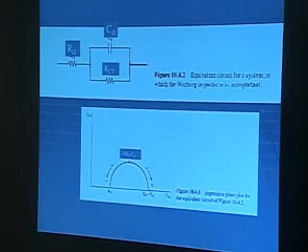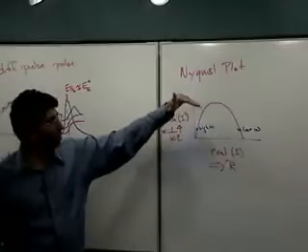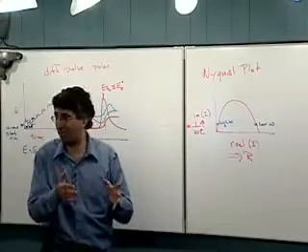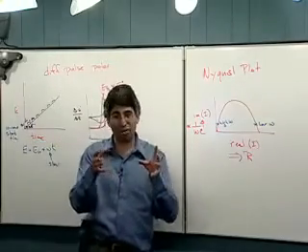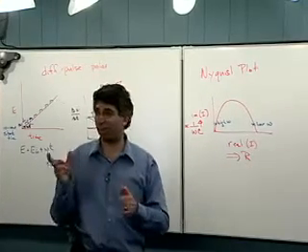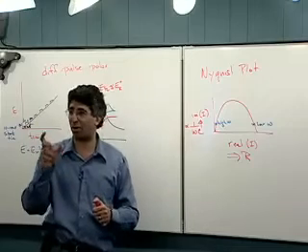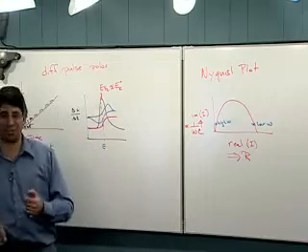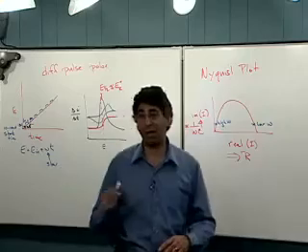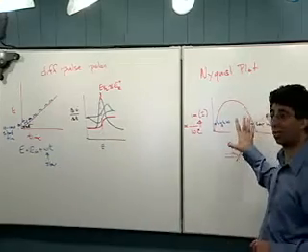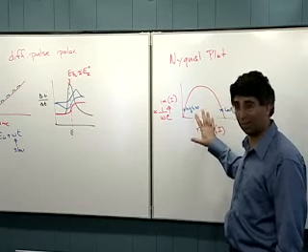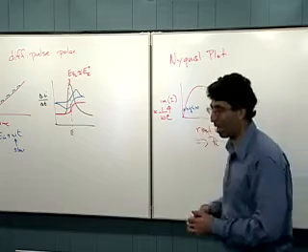Now, the data you're getting out of this is very sensitive to the equivalent circuit. So it will be easy to determine whether the equivalent circuit you draw fits the data or does not fit the data. Okay, so that's the good news. The bad news is we're going to have to take these real-life resistive and capacitive components that we're drawing in our equivalent circuit and try and equate them to chemistry. To the extent that we do that correctly, we get a useful answer, and to the extent that we don't, we don't get a useful answer. The other problem is that we're going to be drawing circuits with several circuit elements in them. And that means that there's probably more than one solution to the problem. There may not be a unique solution, and therefore, again, there's a little bit of a guess going on here.